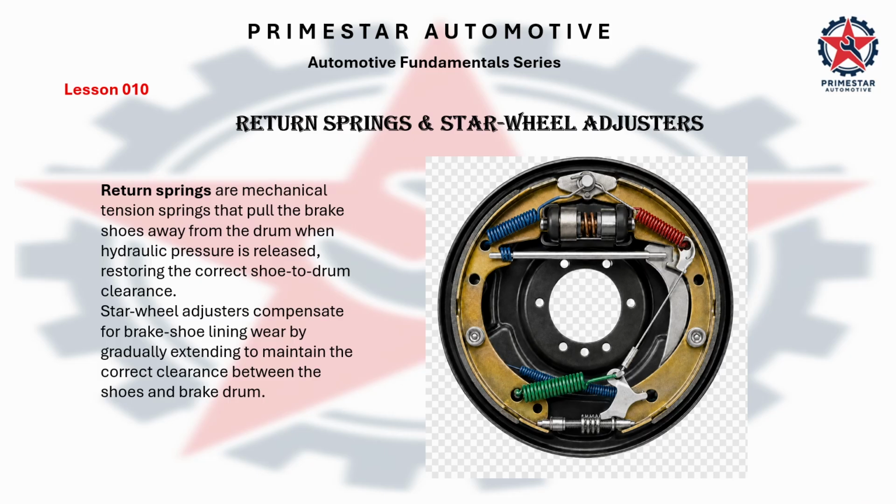Return springs are mechanical tension springs that pull the brake shoes away from the drum when hydraulic pressure is released, restoring the correct shoe to drum clearance. Star wheel adjusters compensate for brake shoe lining wear by gradually extending to maintain the correct clearance between the shoes and the brake drum.